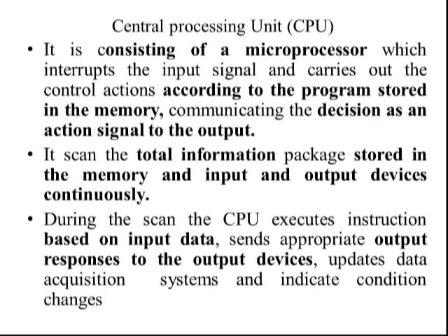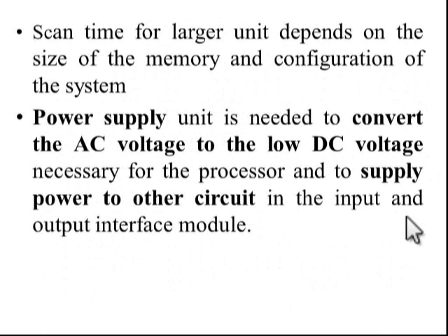It communicates the action signal to the output, so whatever the output, it can be communicated. It continuously scans the total information package stored in the memory or in the input and output devices, and works with respect to the sensors. During the scan, the CPU executes instructions based upon the input data. Whatever data we feed into the input, it can execute wherever it is available. Scan time is very important for the system.